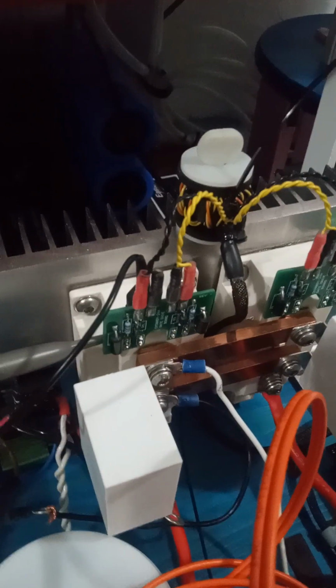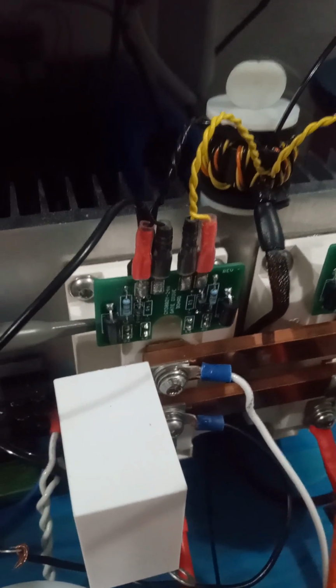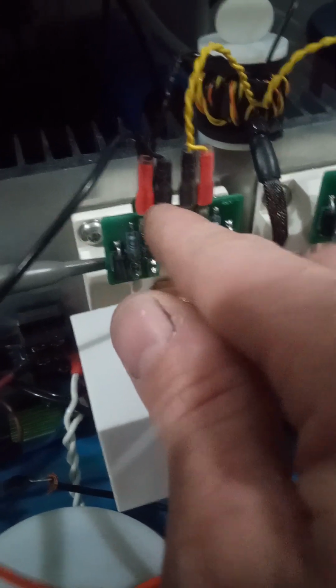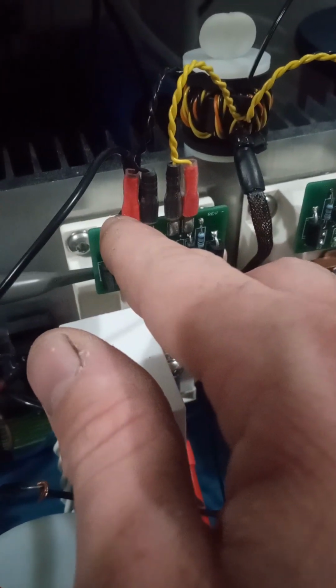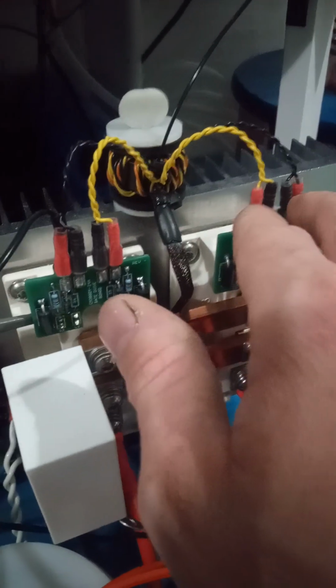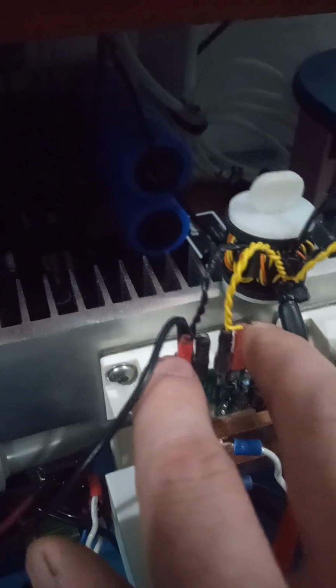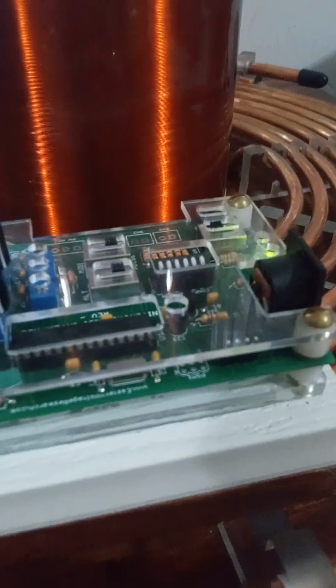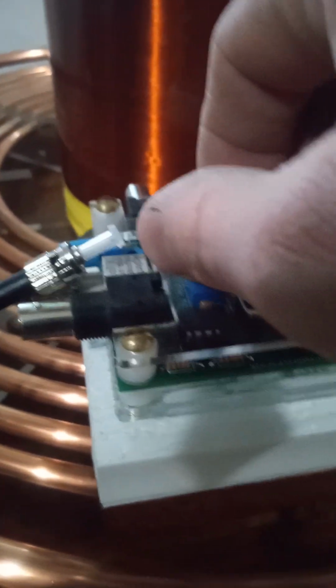Now, when you're checking your switching on your phase, you can basically connect your positive and negative, or swap polarity from your negative to your positive to check if and see if it's switching on or off. And right here, since this has already been gone through, continuity's been checked and the GDT's been fixed. I'm waiting on transistors. I'm going to show you guys how to connect your scope. You're going to connect your scope to the back of the outputs right there at your gates. And using your interrupter, just turn on a small pulse width to where the GDT is switching on.